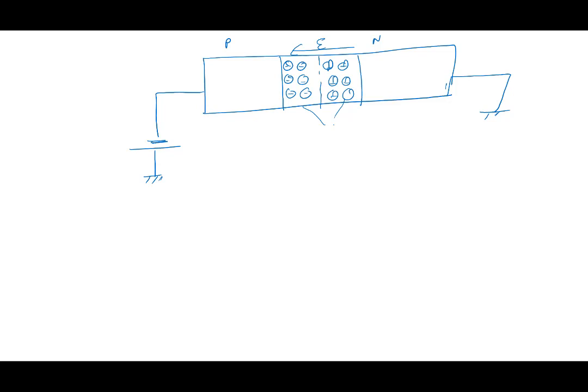So again the charges are changing with field. Again there is a depletion capacitance. Right? Again remember there would be a C equal to del Q by del V. This is the junction charge that you see here, Qj. This is going to change with voltage here. So that is it. In which direction do you want current to flow now?